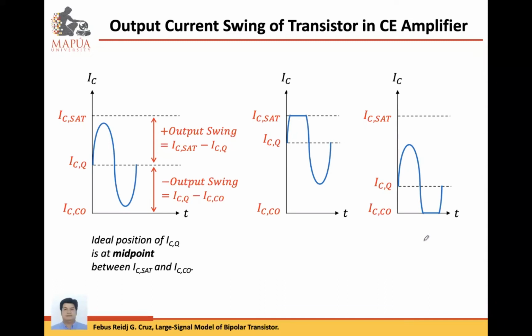So later in our lab, we will design an amplifier and you can observe what happens when there is distortion. You are going to record your voice, and using LTspice, we can convert that voice into input voltage. Then passing through the amplifier, our signal will be amplified.